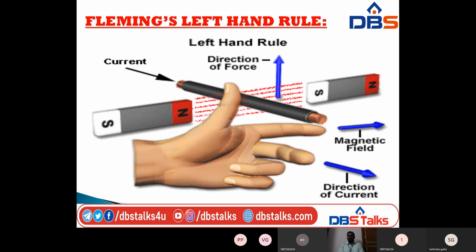Place the left hand like this, and stretch three fingers. This is the thumb, this is the forefinger, and this is the middle finger. The thumb represents the direction of force, the forefinger represents the direction of the magnetic field, and the middle finger represents the direction of current. This is Fleming's left-hand rule. By using this, we determine the direction of force.